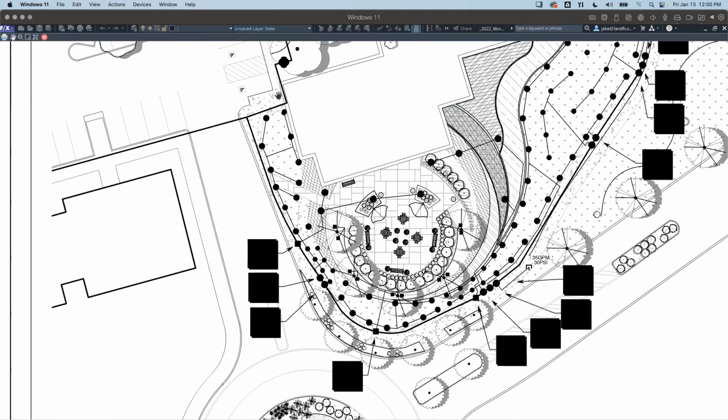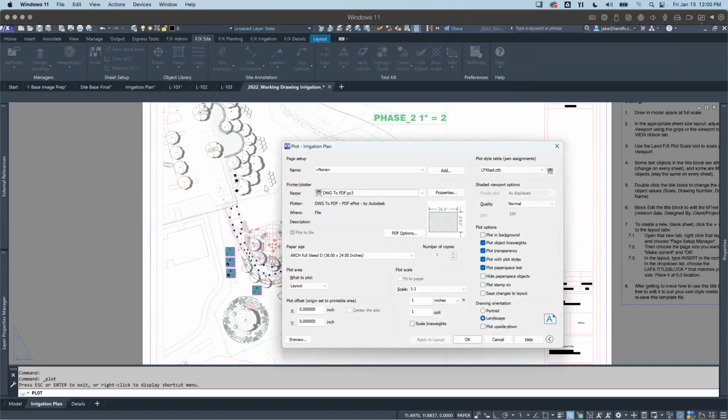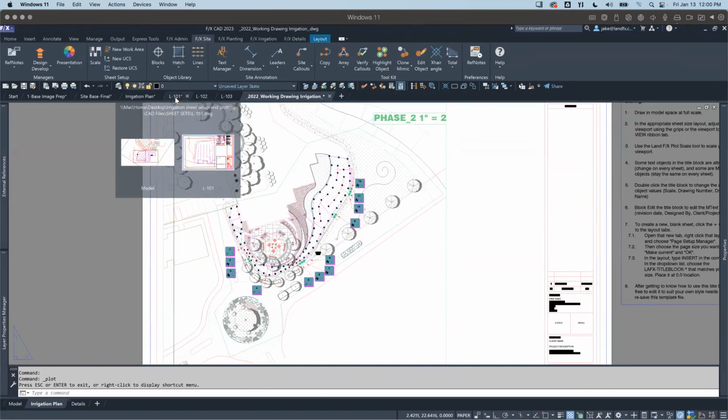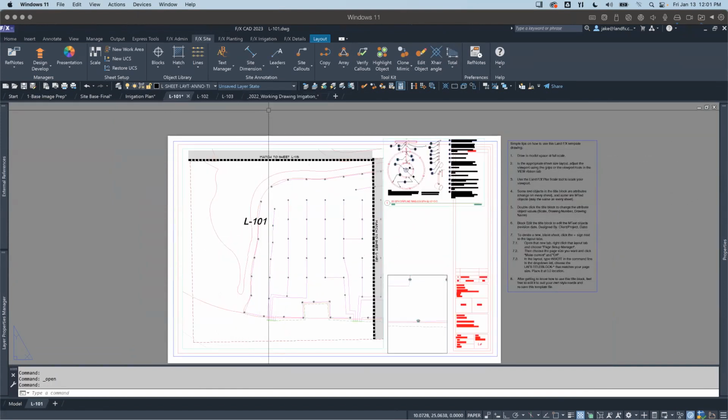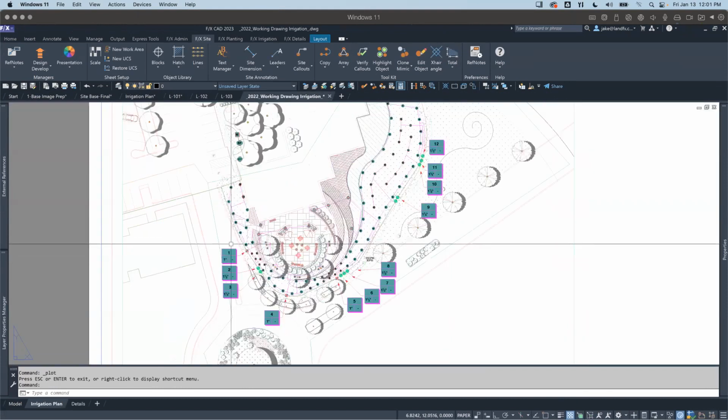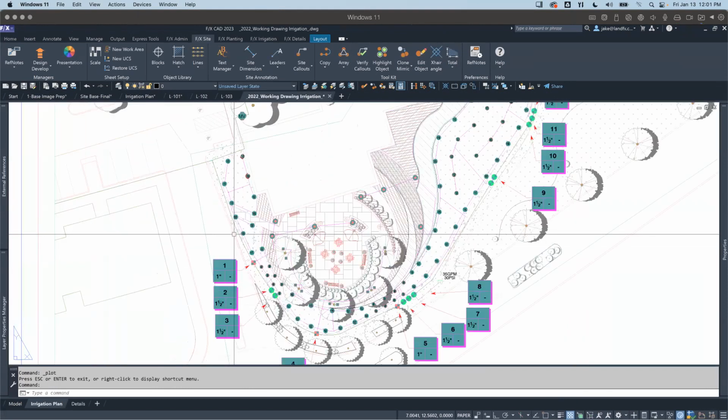So we'll handle this non-dash, the solid line, really quick first. Here again is why we recommend XREFing those drawings into their own sheet file with the PSLTSCALE set to 1, because you cannot have the LTSCALE at 1 and PSLTSCALE at 1 and show the right size without manually adjusting the object types' scale differently.